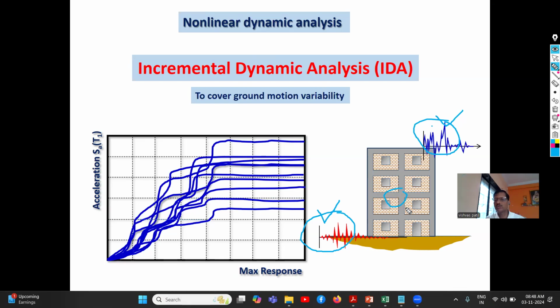This is not a conventional type of structure. This structure is a nonlinear model. Now, how do we convert the conventional model into a nonlinear model? In my previous video, the link is also given in the description, I discussed in detail how to define the nonlinearity and how to assign the seismic nonlinearity to the structure. This is a nonlinear structure on which we are applying the ground motion with increasing intensity, and the outcome of the IDA analysis is this particular curve.